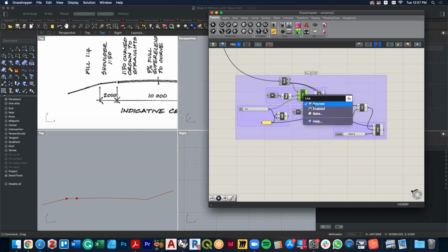So I think the main thing to remember is that when I was reorganizing this, the things I was reorganizing were none of the function, none of the parametric, none of the numbers. I was changing orientation. So I was making Y's negative and X's negative and then changing the starting points of it. When you copy a piece of geometry, you have to change the relational start point, and then you potentially have to change the orientations to make them negative, because we're working down, so negative Y, and we're working negative X because we're working towards the west of the drawing.